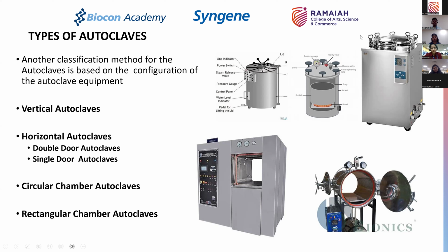So if you look at every modern autoclave today, there is a water level indicator. Some of it is physical. In such modern day autoclaves, there is also an automated system with an alarm. So if the water level is insufficient, it will give you a buzzer saying the water level is not there, I'm not having sufficient water, please do something. And it will have the capability to abort and stop the process so that there is no safety compromise. Okay, so that's the vertical autoclave.